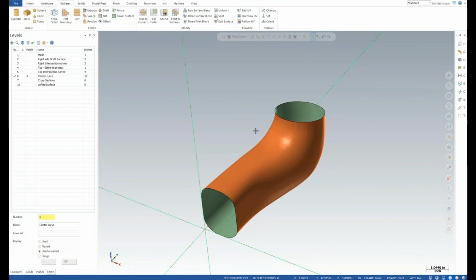Matt, do we have questions we need to answer? There was only one question. Just when you were doing your chaining, they said, can you do a group chain? So I'm assuming they're asking if you could window the chain. You kind of showed that when you were initially chaining, the purpose of it was to get all the start points in the same location. Correct. When I was using the chain on the cross sections the first time, the direction was important because that has a downstream effect on the loft and how the loft syncs up.